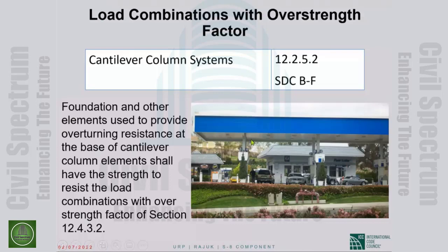So cantilever column systems are where a cantilever column resists the entire seismic forces. It doesn't have to be one column, it can be a series of columns, but those are cantilever columns comprising the entire seismic force resisting system. The entire seismic resistance comes from the connection of the frame to the foundation, of the column to the foundation.